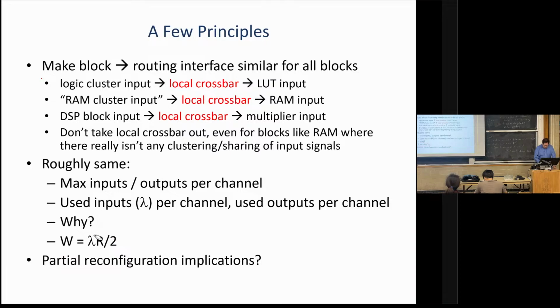This is maybe a hard question. What does this mean for partial reconfiguration? So remember, partial reconfiguration means I'm going to take out a piece of my design. I'm not going to shut it down. I'm not going to reset it. I'm going to program in another piece of something else. I'm going to change the function of this module. And I want it to just hook in to everything else that's already there. So does this have implications for how I do that?